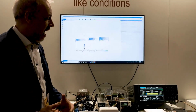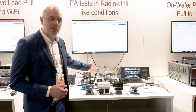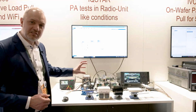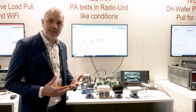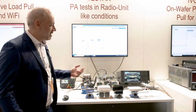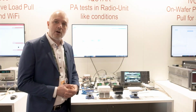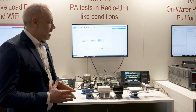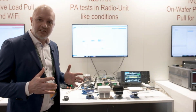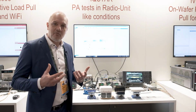So in this application, we have an RF transceiver, an off-the-shelf RF transceiver, which is driven by an FPGA. And this RF transceiver will generate modulated signals in 5G-like operating conditions. And this 5G signal will then be sent to the device, and we will then measure the output power with these modulated signals. Because we are in 5G, we are dealing with very wideband modulated signals, and it's very important to optimize the performance in terms of linearity.